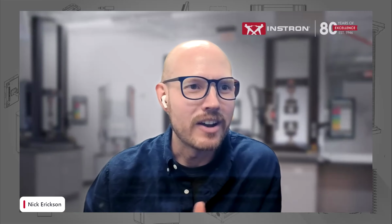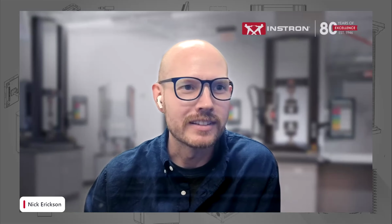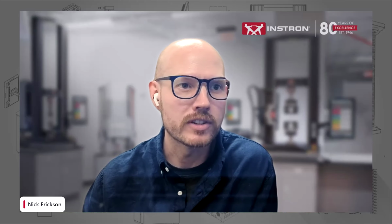All right. Now we have a question about cylindrical samples. Any advice on using AV on cylindrical samples? Is it still able to track dots over a curved surface? Yep, definitely still able to track dots over the curved surface. It's still going to be calculating and finding that centroid of however you're marking your specimen. So there's not a concern with round specimens.